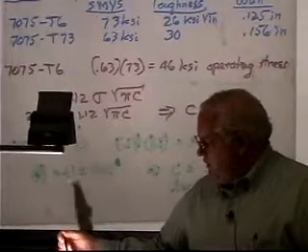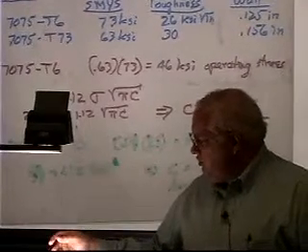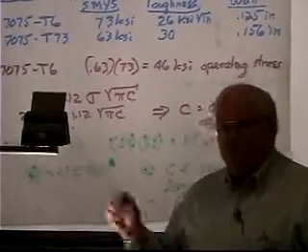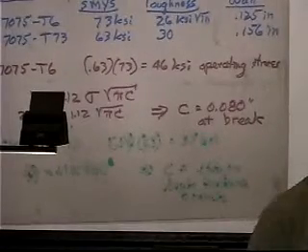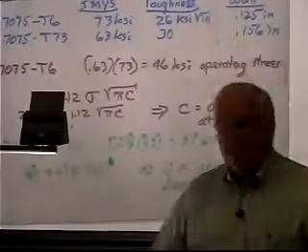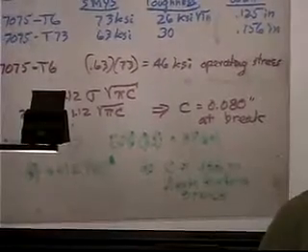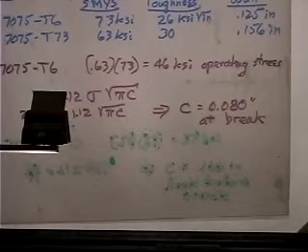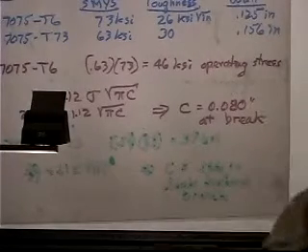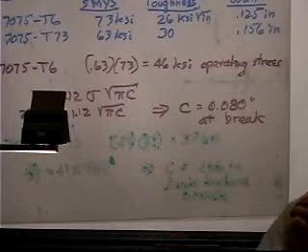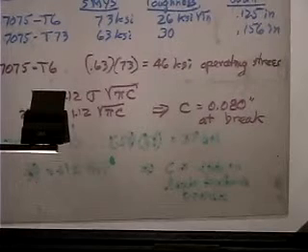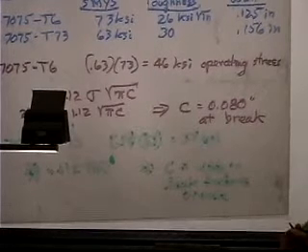And you can't read this very well, but if you go through this, you find the critical flaw size is about 4.5mm. And the thickness is only 4mm, or just under 4mm. That means that you actually get leak before break. You actually squirt out a little bit of oil before you get the whole thing split in two.